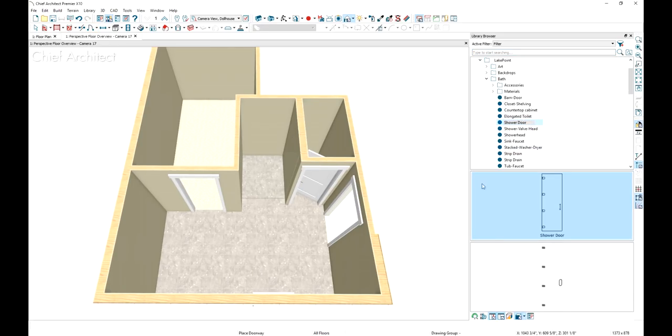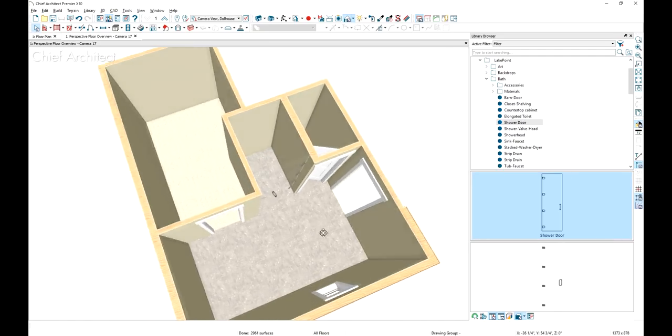And what I've done here is I've created a favorites folder. To save that, let's go ahead and flip that door swing area around. You'll find a tool down here to flip the swing and the hinged area, and then you can bump that against the wall. With the doors in place, let's go ahead and switch and place a few of our windows.